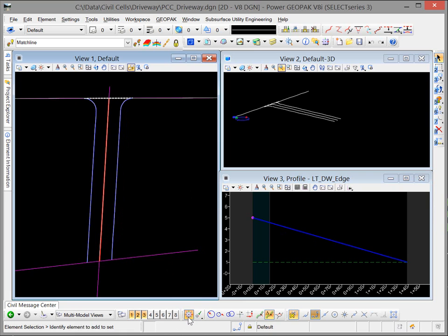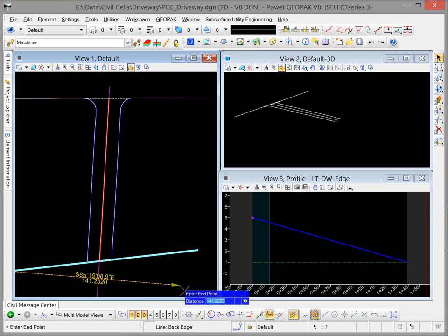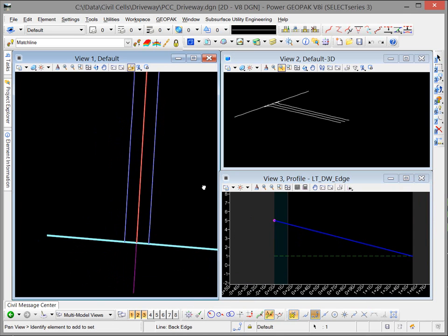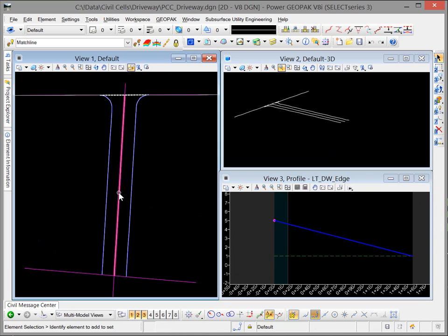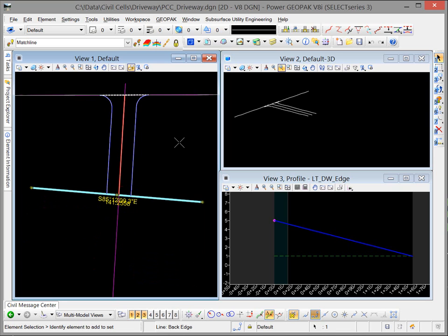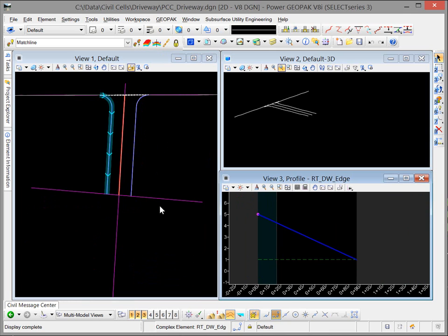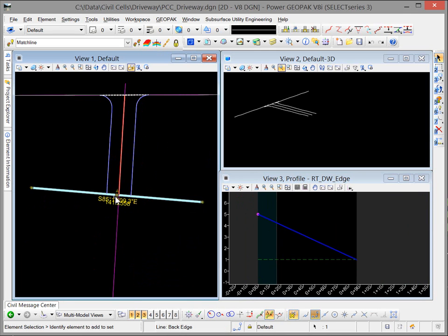And so we'll turn off the Civil AccuDraw, and one of the things that you can do is as you wiggle this, all of your profiles should adjust appropriately, and it looks like they are. If I come into this particular line, or I'm sorry, the reference line, and I slide that up, I should see our profiles modify as such. And so I come over here and open another profile window just to check them all, and that's always a good idea to check all of them, make sure they're all reacting properly. And so you can see that adjusts perfectly.